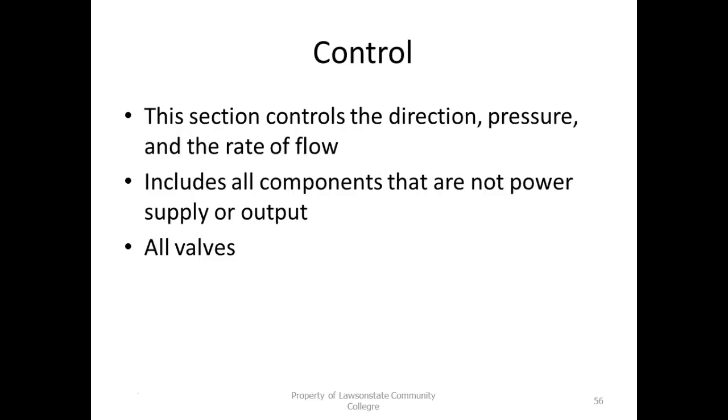So if I've got what we call a double acting cylinder, we'll put pressure on one side to make it retract and exhaust the other, right? You understand? Or we'll swap the exhaust and the pressure to cause the cylinder to move in both directions. So these are directional control valves. And I think the next chapter is on directional control valves.